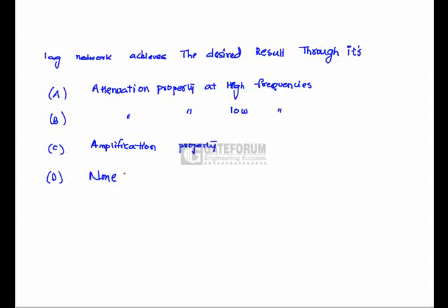The lag network achieves the desired results through its... See, lag network is nothing but a low pass filter, means it suppresses the high frequencies. Hence, it exhibits an attenuation property at high frequencies, hence option A is correct.